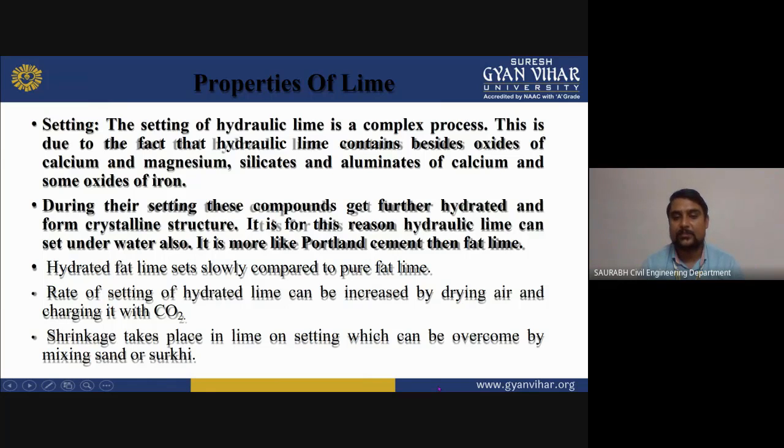Hydrated fat lime sets slowly compared to pure fat lime. The rate of setting of hydrated lime can be increased by drying air and charging with CO2. And shrinkage takes place in the lime on setting, which can be overcome by mixing sand and surkhi.